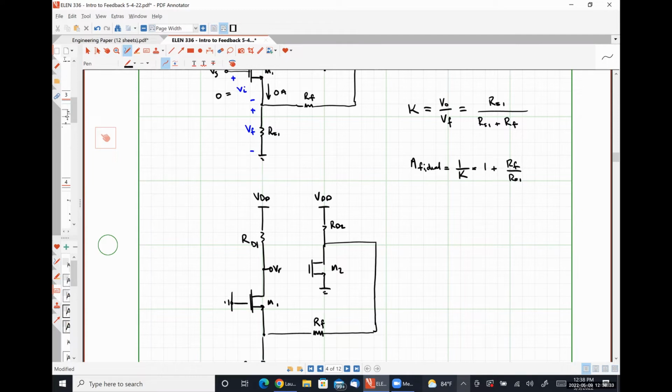So this is our return voltage, and then here is where we're going to apply our test voltage. And the reason why I'm choosing to break the feedback loop here is because this is the easiest place that I can find in the circuit, which should satisfy our criterion of not changing our open loop gain while also not changing whether or not our feedback loop is loading our circuit. Okay.